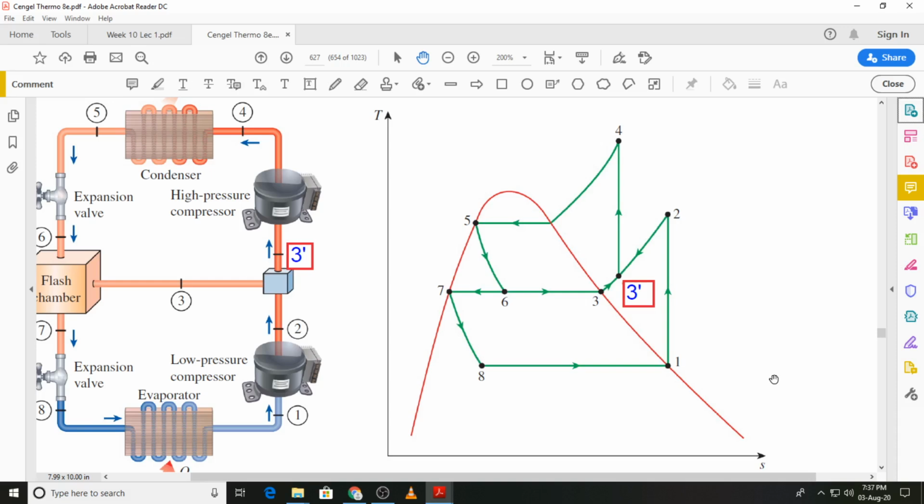over here this is not the exact cycle that we are working with, and I'll show you where this needs modification, but the basic arrangement is the same. You can see the state points 4, 5, 6, 7, 8, 1, 2 and 3 prime. State 5, so we have the isenthalpic expansion from 5 to 6, and that is the isenthalpic process line on the TS diagram. Similarly, we have the isenthalpic expansion again from state 7 to the evaporator pressure, that is at state 8, and this is again an isenthalpic process from 7 to 8. Then you have the heat rejection from 8 to 1.